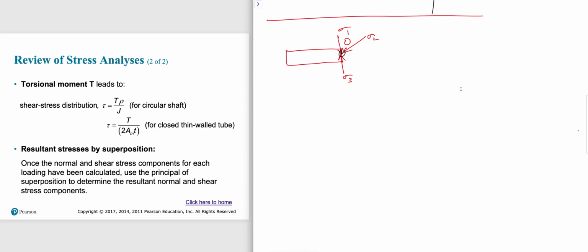So basically we take all the stresses in one direction. So if we take Y, we take the net amount of stresses acting in that direction. That's basically superimposing. So sigma 1 going down, let me write it negative. Sigma 3 going up, let me write it positive. So positive sigma 3, negative sigma 1, and I need to give you this angle, theta. Because the area is the same, sigma 2 cos theta is going down, so negative sigma 2 cos theta. So that is basically the net stress acting in the y direction. And that's basically the concept of superimposing.